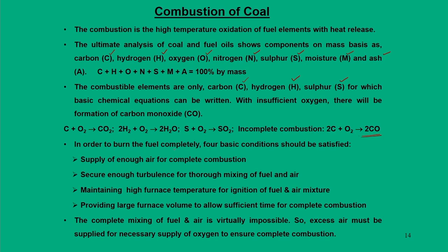To burn the fuel completely, there are 4 conditions that should be satisfied. First, we should supply enough air for complete combustion, and when you say enough air, we should make proper mixing of fuel and air. So, we require enough turbulence and thorough mixing. Then for this air and fuel mixing, your furnace temperature should be very high, so that it can ignite the fuel and air mixture.